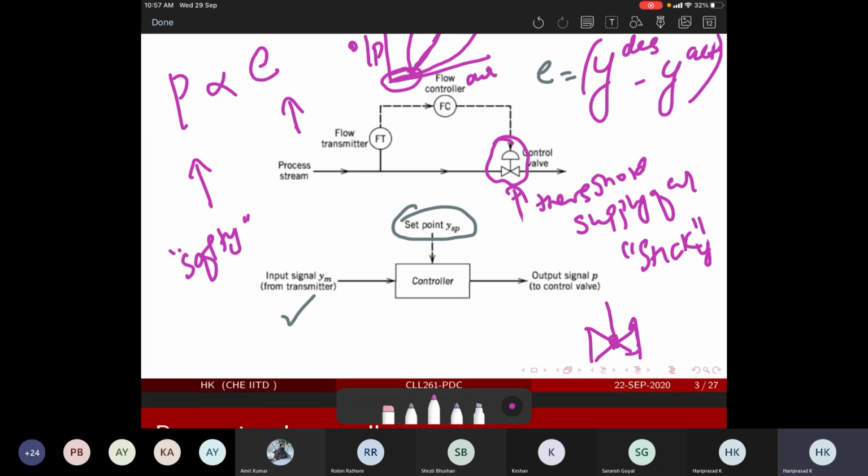See this valve head, right? It is fixed over here. This is metal, most likely. And there is a diaphragm, as we told. So unnecessary movements of these mechanical parts, be it a diaphragm or this valve, will lead to erosion, which is a huge maintenance work. Once the head is eroded, you will have to change the valve.